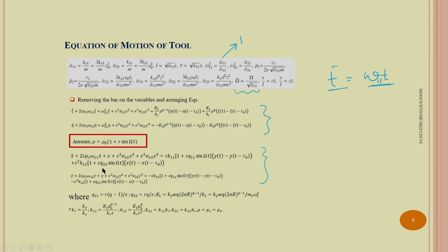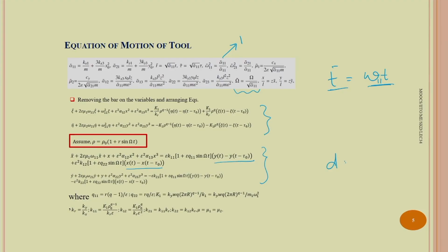You just see this equation is written in the form of a delay differential equation. Here the delay part is considered in this equation. So, you can solve this delay differential equation using the DDE23 command of MATLAB, or you can write your own equation solver to solve these things.